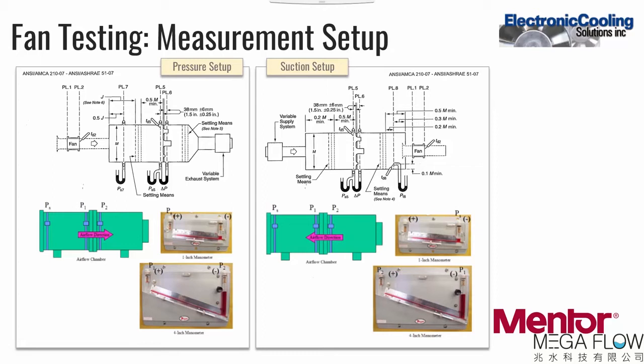For the free delivery condition, which is one extreme of the PQ curve, the fan is set at a speed which needs to be characterized. The variable centrifugal blower on the other end of the chamber is adjusted so that the static pressure probe reads 0. It is necessary to use the centrifugal blower to overcome the impedance caused by the air passing through the nozzle plate and the settling mesh screens in order to create a zero static pressure condition.